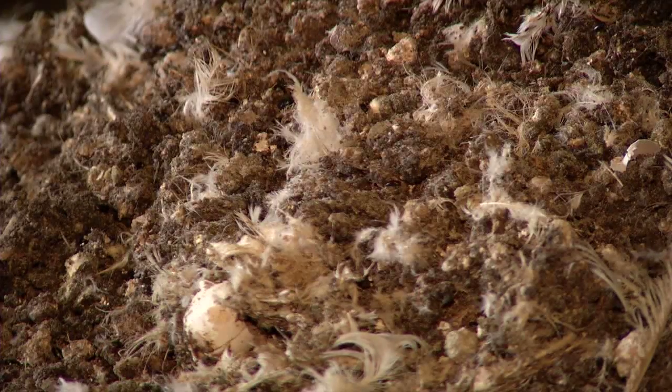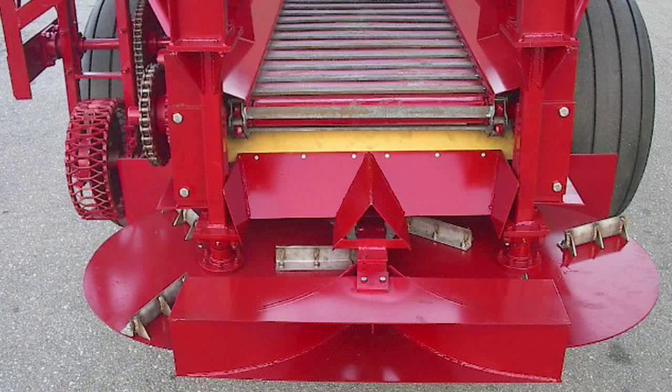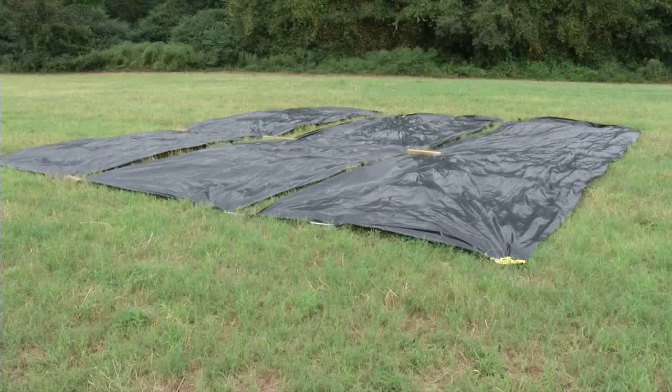Again, your swath spacing is affected by the density of the material. Also, angled spinners will usually give greater swath spacing than flat spinners, and higher spinner speeds will also increase swath spacing. The last step is to determine the application rate.